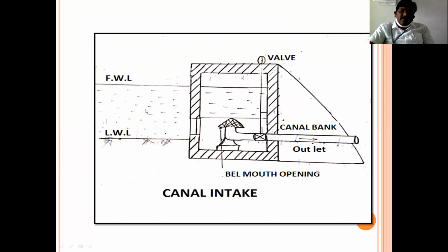The water passes through the screener and enters the brick chamber. Here in the brick chamber, at the bottom, we keep the pipeline like this. Even that pipeline has one screener. There are two screeners: one at the pipe, and the other at the entry itself. By keeping the screens like this, we can avoid the entry of unwanted particles, or even small fine particles, into the pipeline.